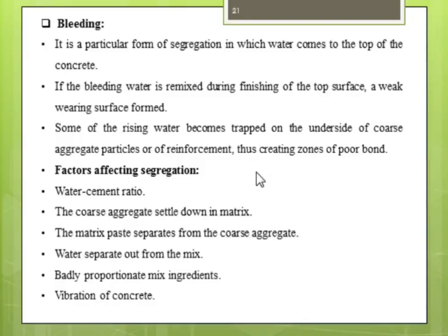Or from this formwork, if there are some leakages or gaps in your formwork, the cement paste flows through those cracks, so that is also bleeding. It is mainly affected by the water cement ratio and a higher admixture dose. This is also not required, because cement paste is the heart of our concrete, since the complete hydration process and whatever binding property there is are all in our cement paste.